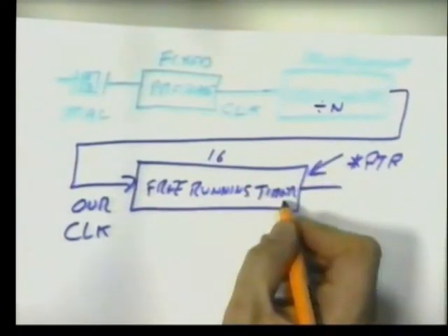You can read that time, you can write it, you can reset it. Now why is this leading me up to interrupts? Because there are a whole variety of interrupts you can generate based on this free running clock. So if we have this timer, a free running clock, and I'm going to now refer everything to the free running clock.